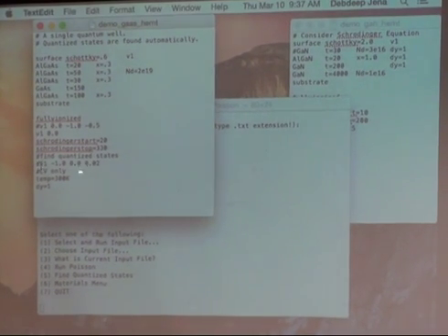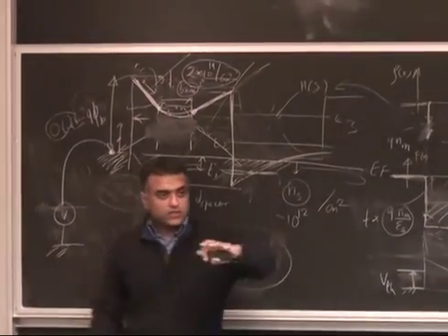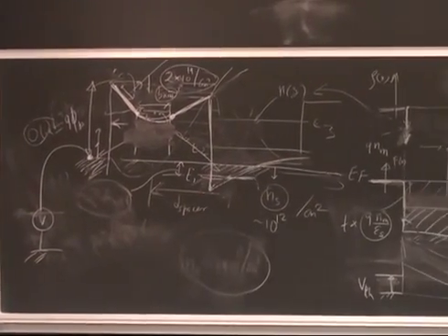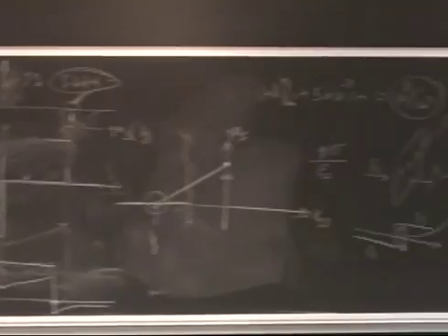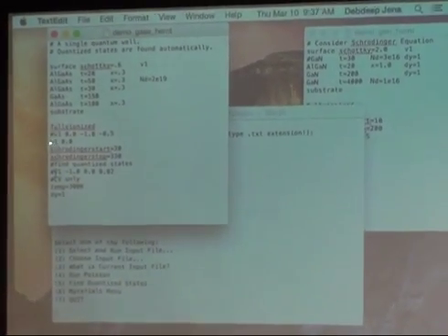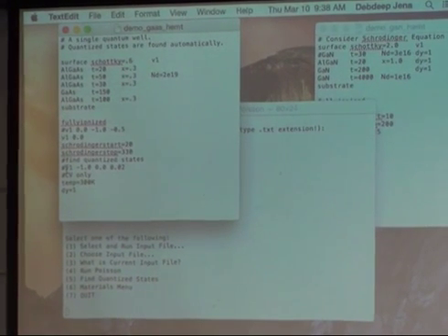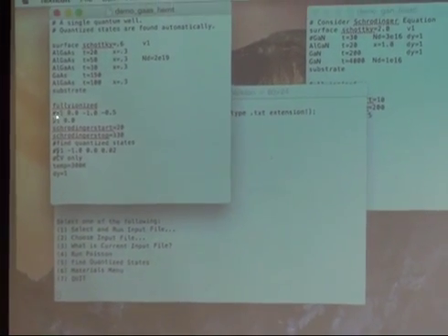So basically, if you say that I'm going to put the gate on the surface, here's my Schottky barrier height, 0.6 eV. That's what it's doing there. I've chosen a metal which put on the surface gives a Schottky barrier of 0.6 eV. Here's the structure we just talked about. Here's the modulation doping. And the voltage on the surface that I showed you earlier is the equilibrium, no voltage on the gate.